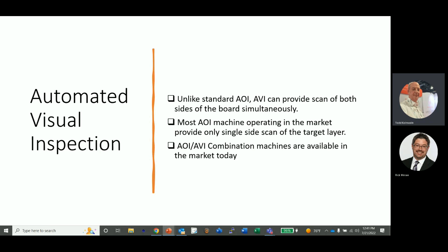And Ricky, when we're talking about this, the question comes up on the AVIs, what they can detect and all the anomalies that you talked about. Another thing it can find out for you, although the colors of mask and nomenclatures, is it can also dimensionally check your board. So if you have pads that are supposed to be a certain size, it can double check that, or your annular ring is supposed to be a certain size.